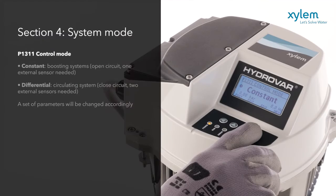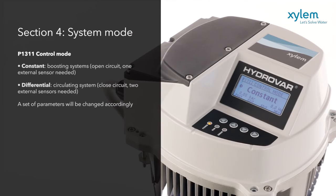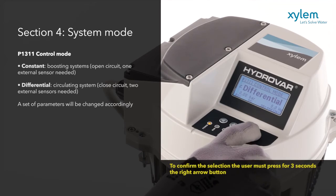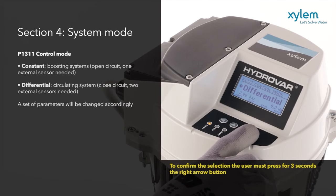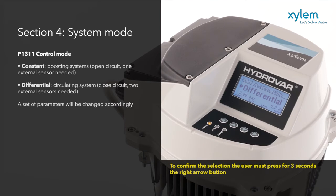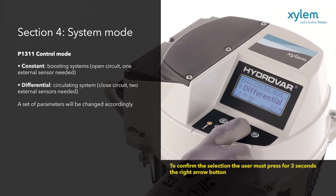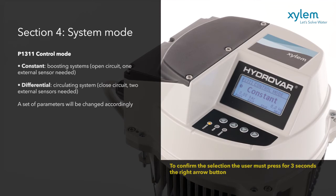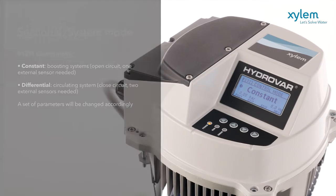In control mode, you can choose between constant for constant pressure systems or differential for closed loop systems. The parameters change on screen accordingly. Remember that constant pressure requires 1 pressure transducer, while differential pressure requires 2 pressure transducers. There are other options.